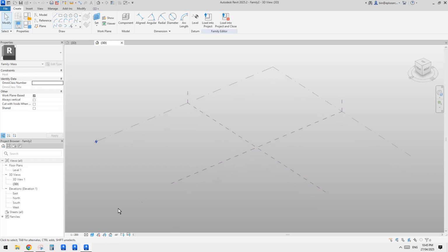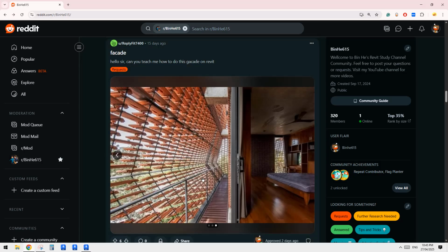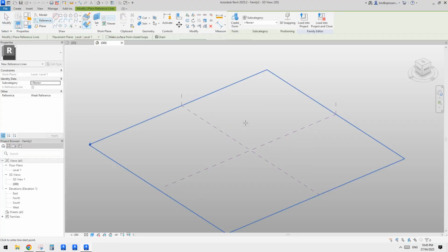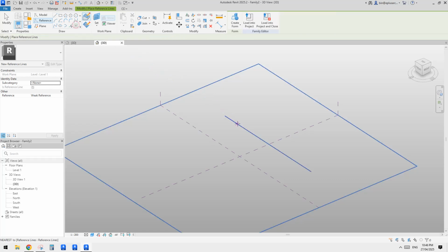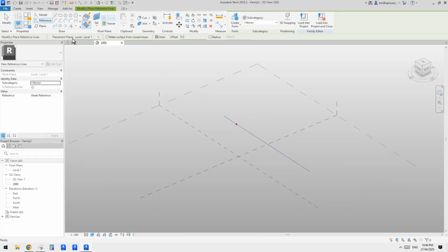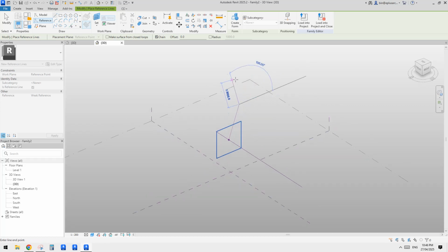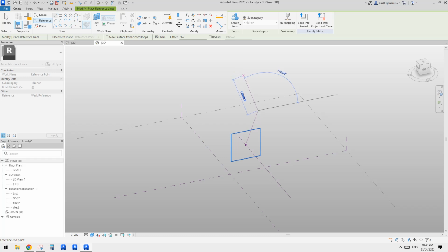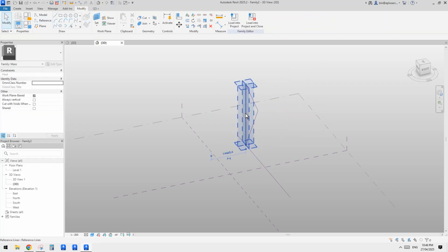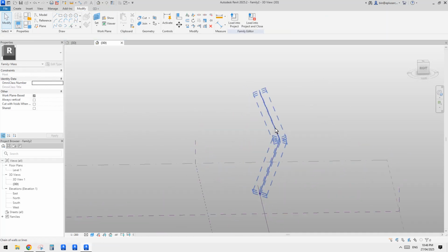Okay, so in this mass, we're going to create something like this, right? So, very simple. I'll just create maybe a sweep. Okay, sweep. So let's first do a reference line. Okay, and place a point, and place a reference line onto this point. So I'll just choose an angle, maybe 70 degrees. So another one, so it will be 110. Doesn't work. Anyway, so I'll just do this. Go up, TR, trim, and delete this one. So okay, now we have this and this.